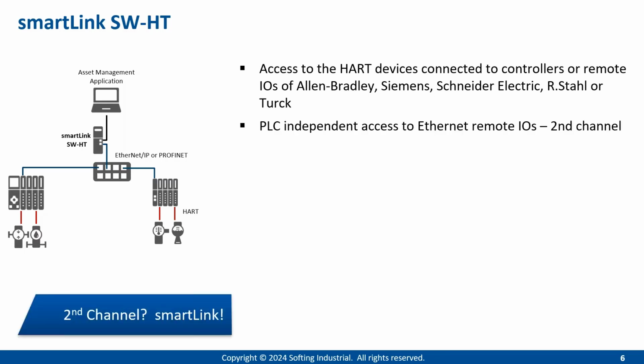The access to the HART devices is independent of the controller you are using. If you see this path from asset management via remote IO to the controller, we are not touching the communication from the controller to the remote IO. What we are establishing here is a second channel from your asset management application to the HART devices. That's done via our smartLink software solution.